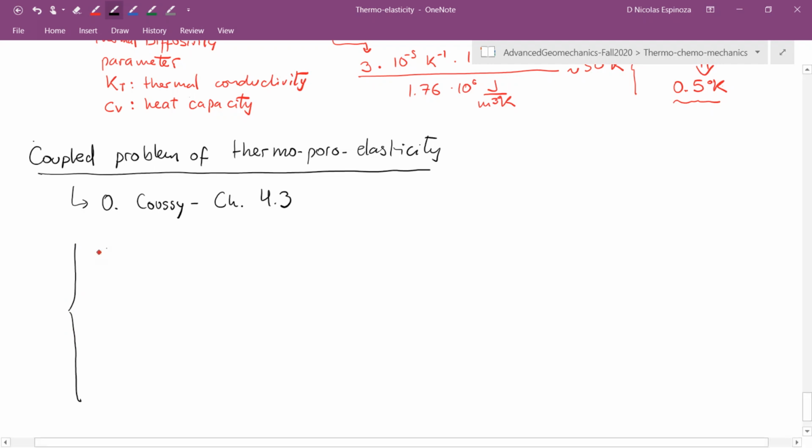First of all, poroelasticity, we saw that it had three equations. One for the mean stress, in which the mean stress depends on the drained bulk modulus, the volumetric strain, pore pressure through the Biot coefficient alpha, and now I'm going to have the additional term, which is going to be the volumetric stress term caused by thermal dilation or contraction.